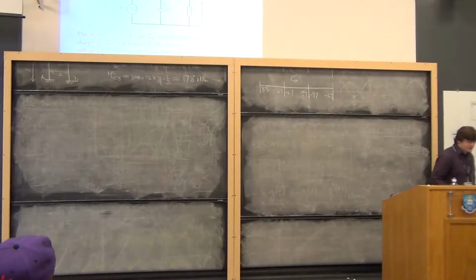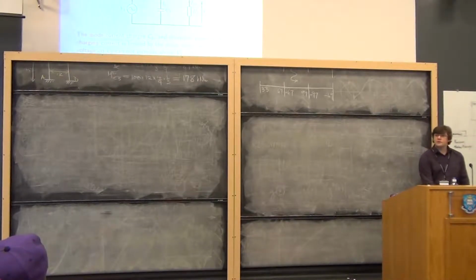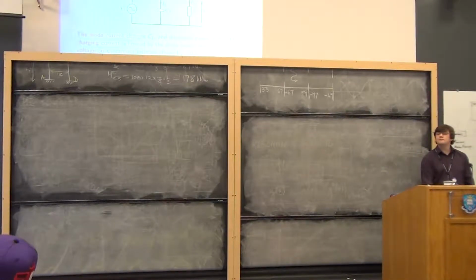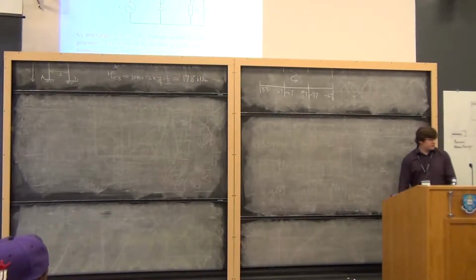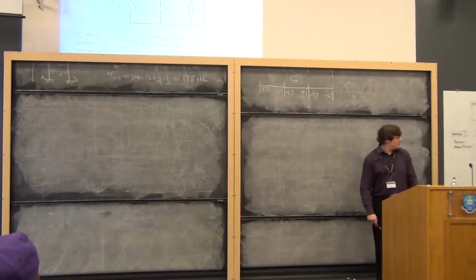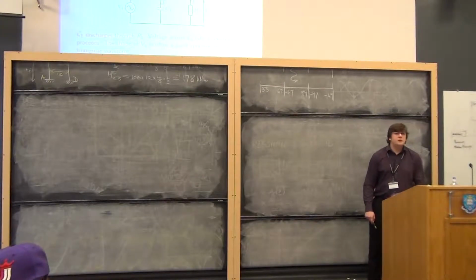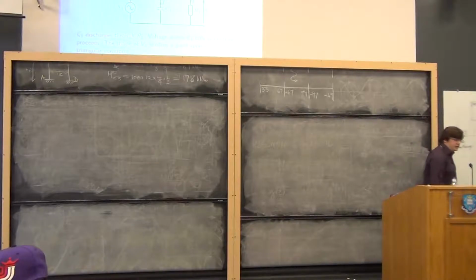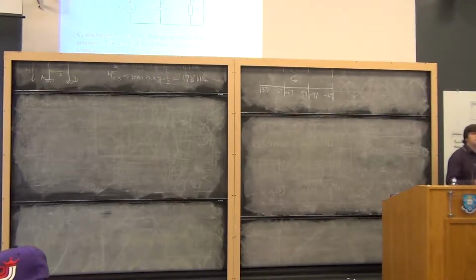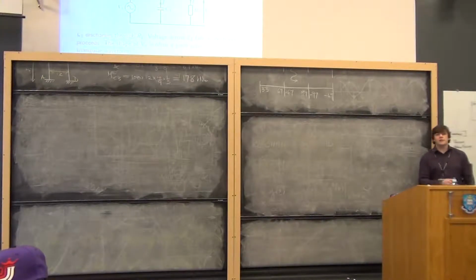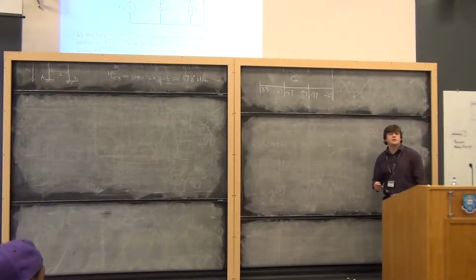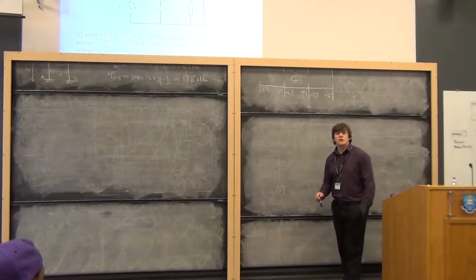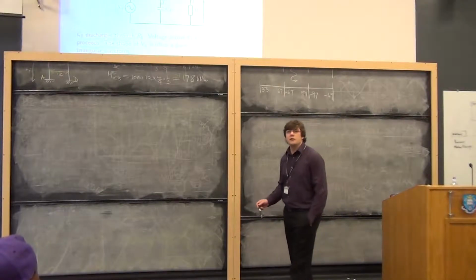So it's V1 minus 0.7. Sorry? So what about the state when it's not conducting? Well, we can just remove the diode, same as usual. And in that case, a current must leave C1, assuming C1 has previously been charged. If the whole situation is in the state of quiescence, where there's nothing going on at all, C1 is uncharged, there will be no current in R1.